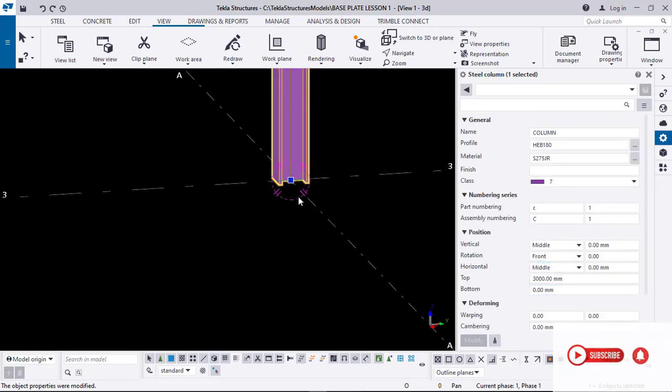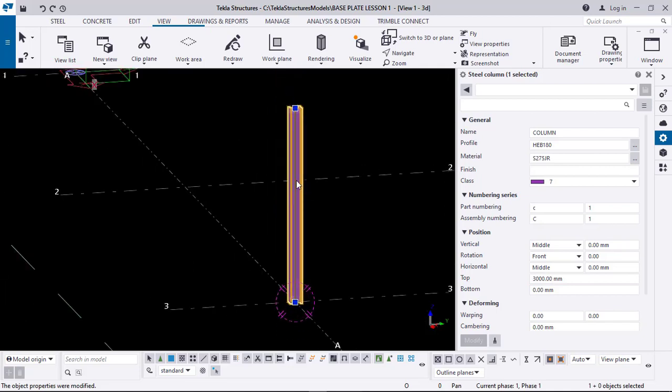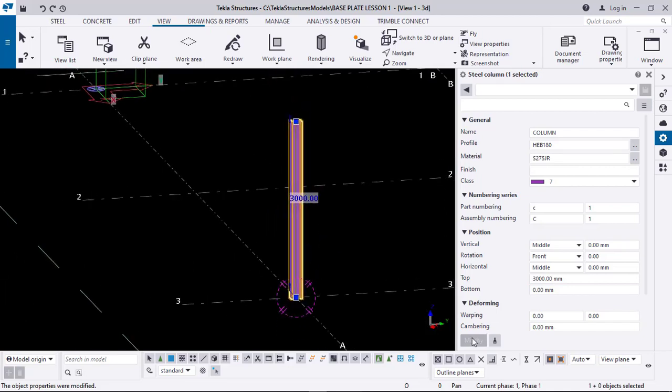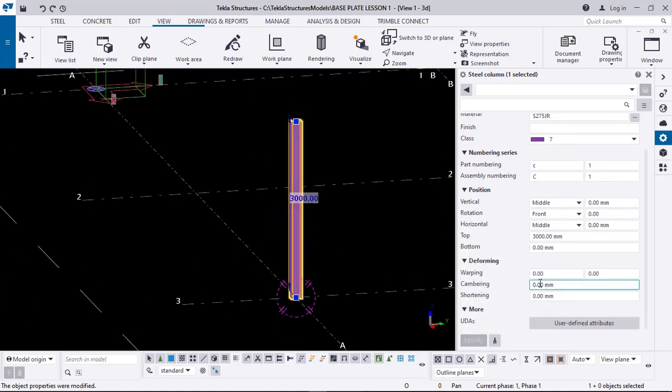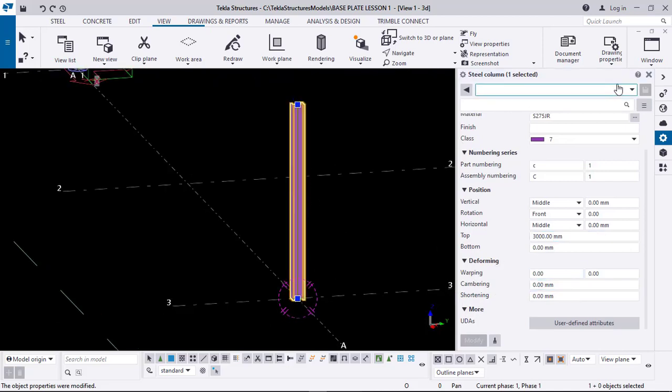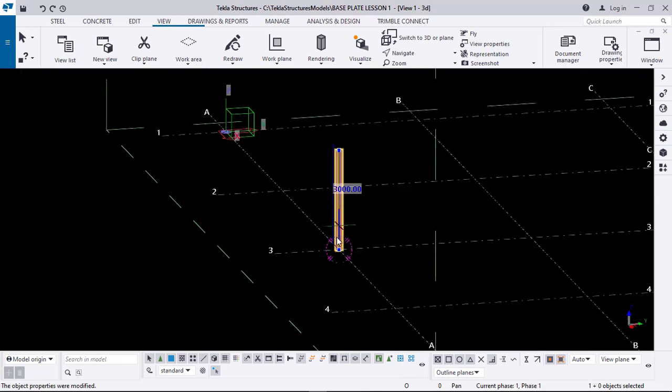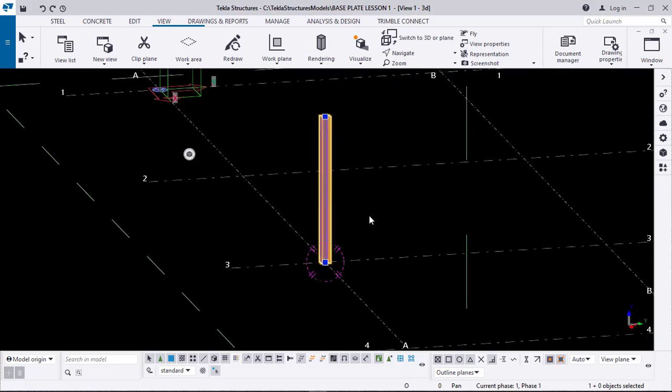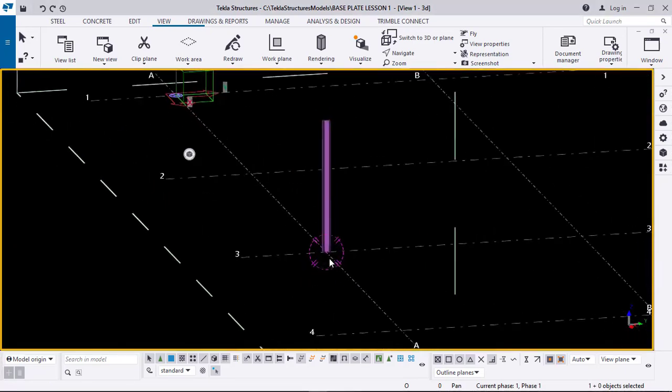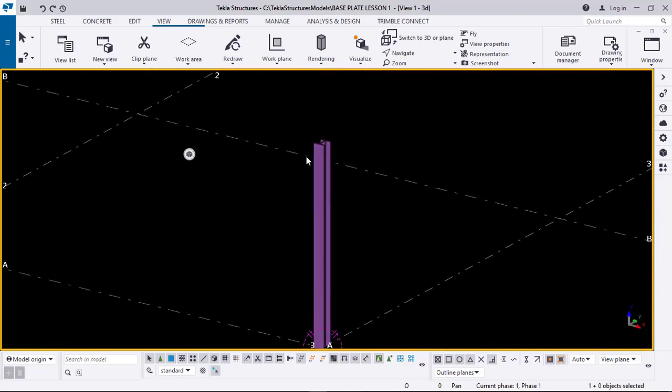Okay, so knowing this, you can see that we have done this column settings. Since we clicked on modify, you just leave every other thing here as default. Now if we close this, to insert the rest, just click on escape. Okay, now if you rotate, you can see what we have just inserted.